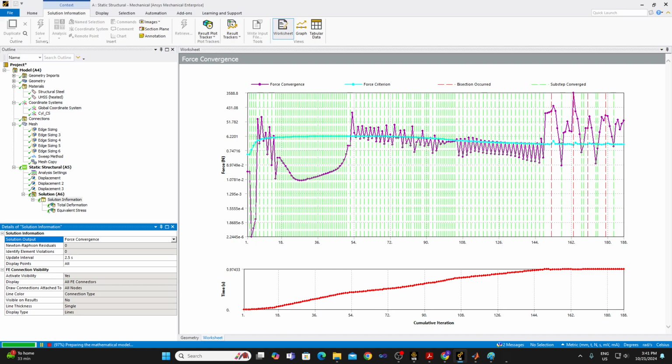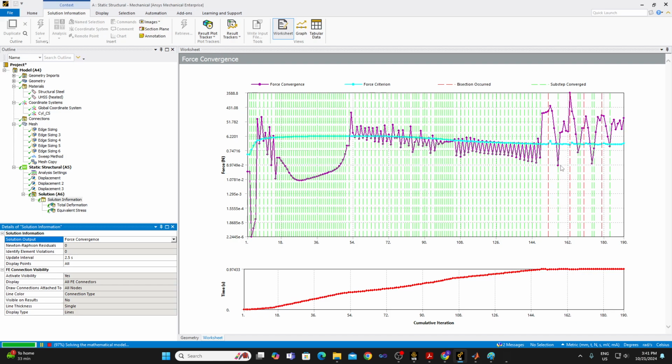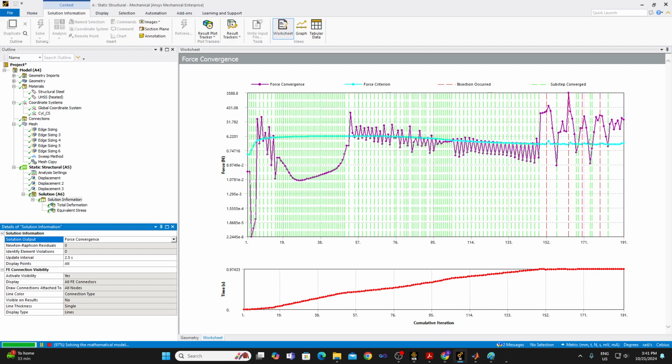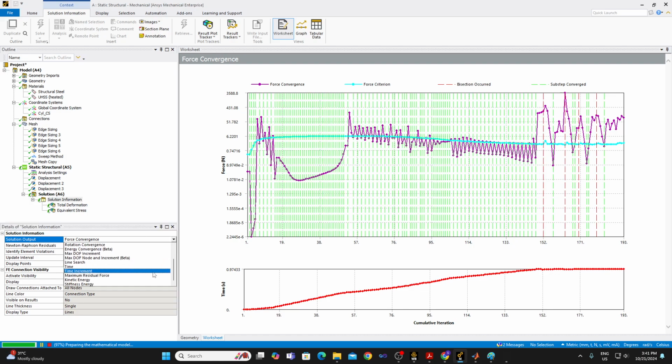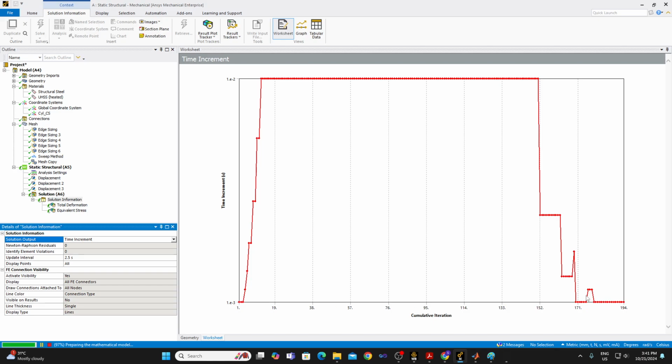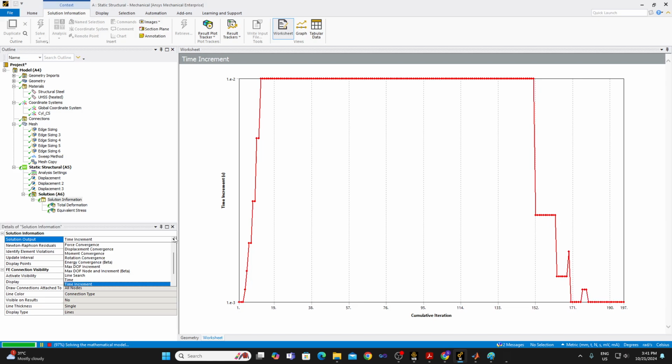Then maybe it will converge. At times, with several iterations, they do not converge, and with multiple bisections happening, the time step size falls below the lower limit. Currently, it is at the lower limit. If any further bisection happens, the solution would be stopped.